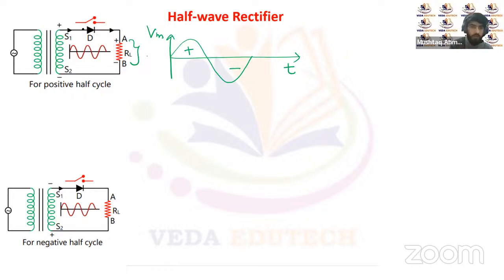You can see here is the diode connected. For the positive half of the cycle, the P type will become positive and the N type will become negative, so this diode will conduct.